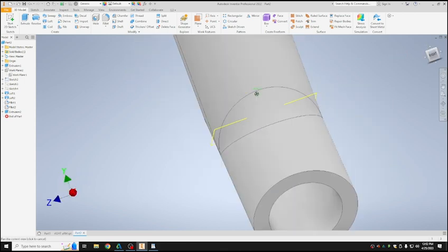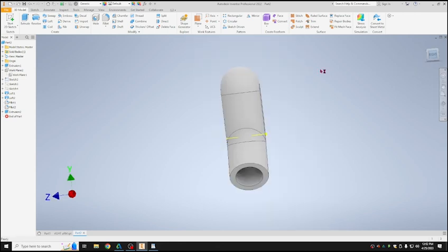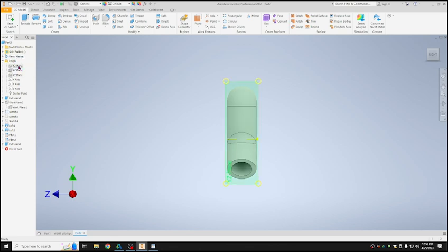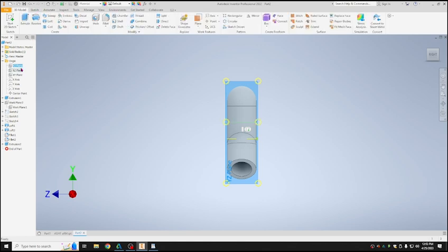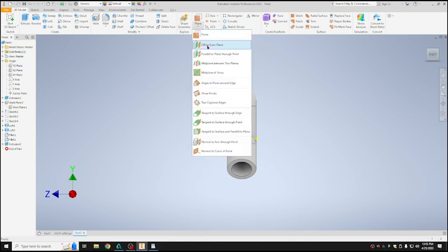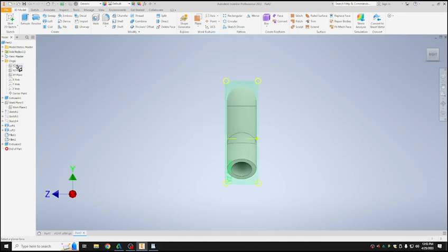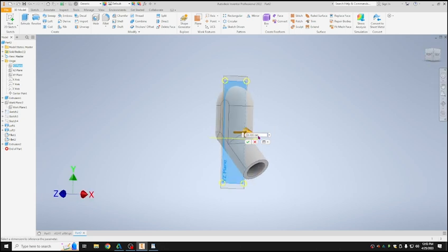All right, so let's go ahead and zoom out. And what we're going to do now is create a new offset from our plane. If you open up the origin folder over here, okay, we're looking for the YZ plane. There it is. Oh, I screwed the order of that up. Go to the top of your screen, 3D model, hit plane, hit offset from plane, and then select your YZ. How far are we going to offset it? We want this offset by 3 millimeters.